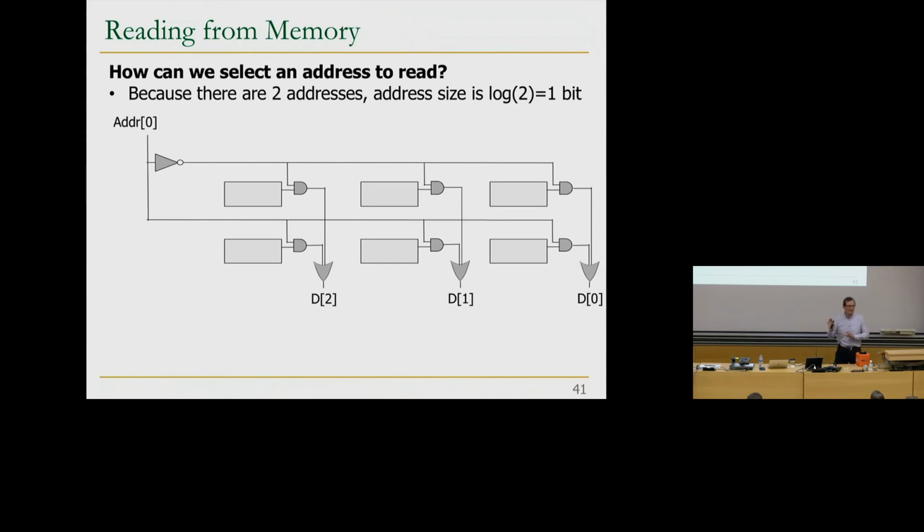Okay, you've seen the circuitry before. Remember, this is an address, we're matching a pattern. It's a pattern matcher. So what I've shown you over here is a word line, and that's an address decoder. We've seen the decoder before, right? This is a very simple decoder, a 1-bit decoder. Remember, a decoder is a circuit that looks at the input value. It has n inputs and 2 to the n outputs, and it asserts only one of the outputs depending on the bit pattern on the n inputs.